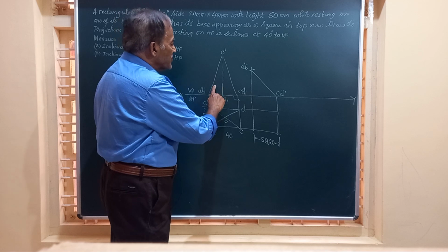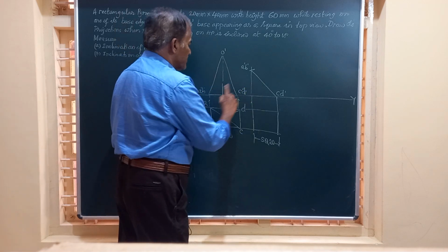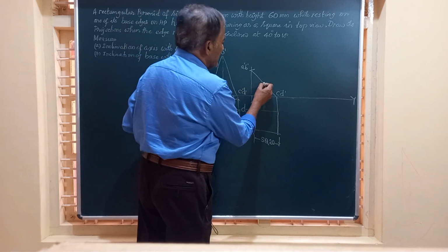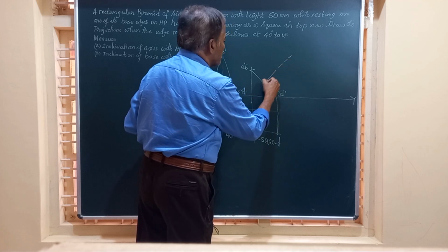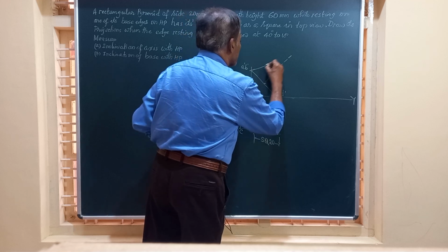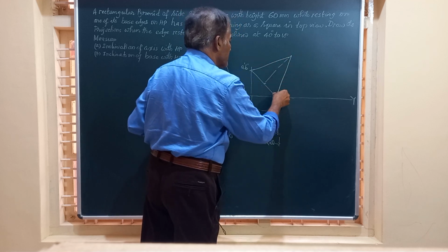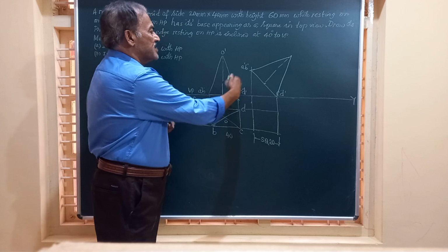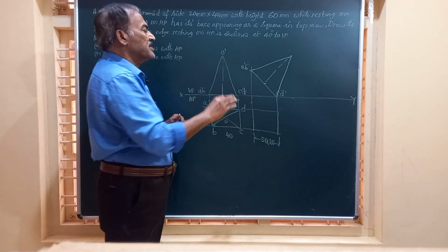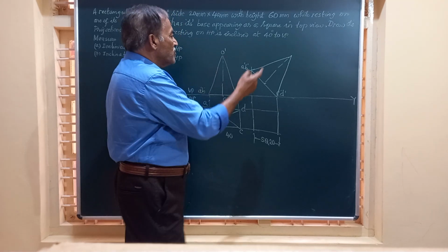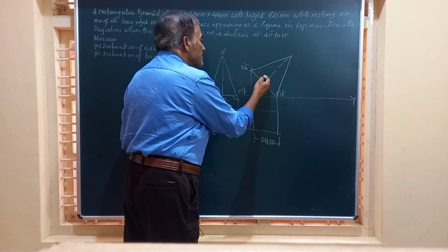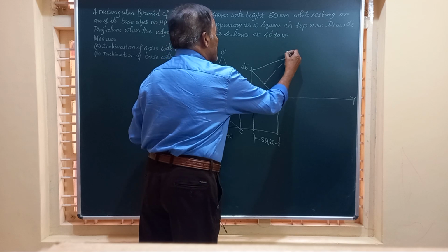So we have to reproduce this figure on this. So this is the base I have drawn here. Locate the center of that, and you know the height of this object. Join that. And remember, whenever you are drawing this second figure, in case of all the solids and the laminae, it is going to be a photocopy. This is the photocopy of this in all respects.